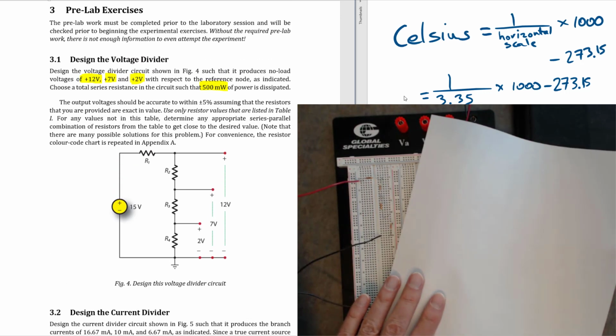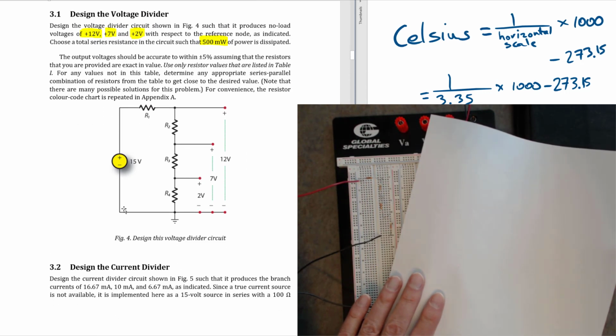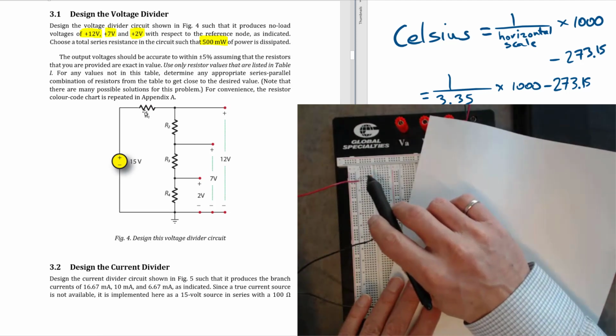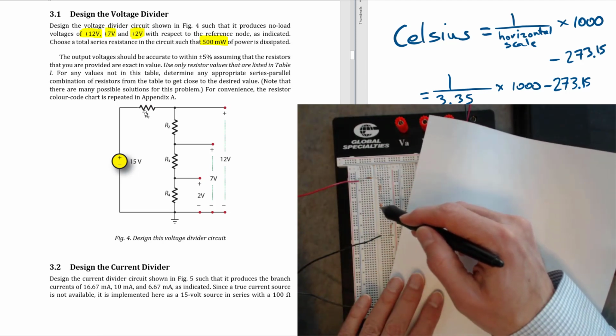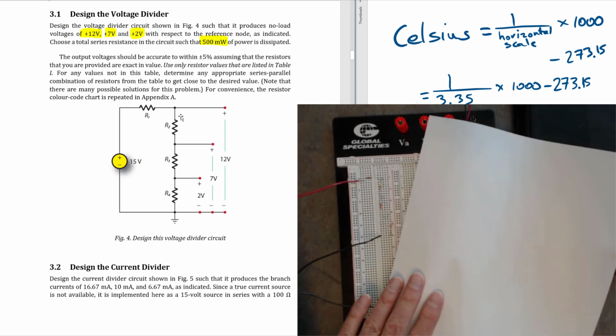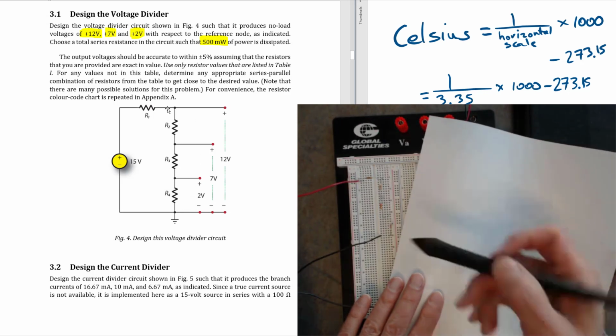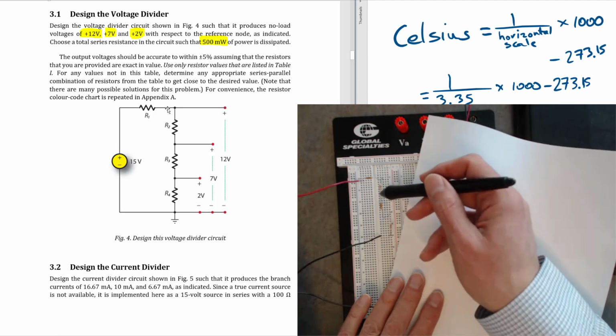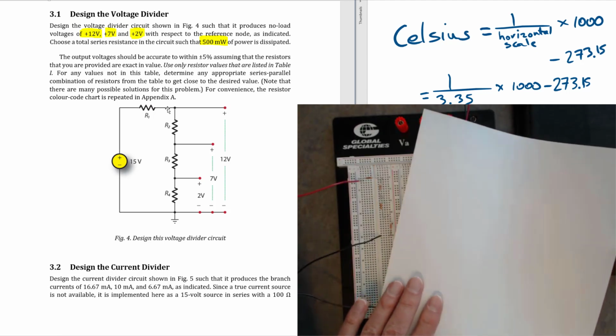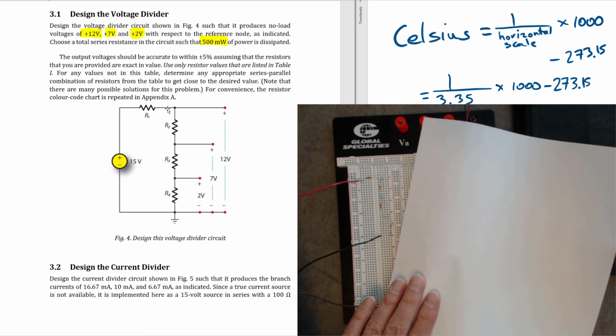We can see that there's a correspondence between this circuit and the voltage divider, okay? You see how we have the source on the left hand side, the 15 volts, the R1 resistor horizontal, so that's over here, okay? And then we have the 3 resistors coming down, so that's these resistors here, okay? And then we can make measurements across these resistors to check the values, okay? So that's how we build the voltage divider circuit in a way that looks like the circuit in the diagram, and it's going to help our debugging quite a lot.